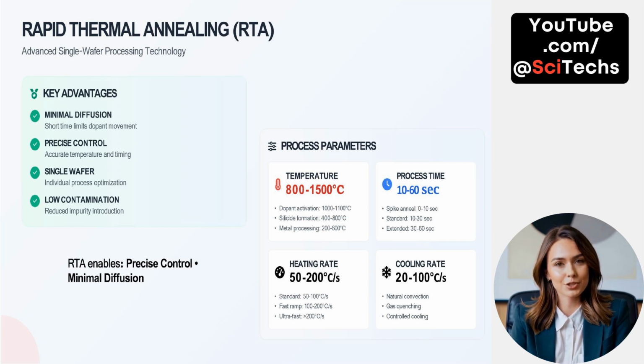The process time is short, typically between 10 and 60 seconds. Heating and cooling rates can reach up to 200 degrees Celsius per second and 100 degrees Celsius per second, respectively, supporting fast thermal cycling while maintaining device integrity.